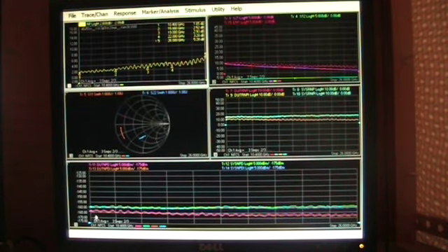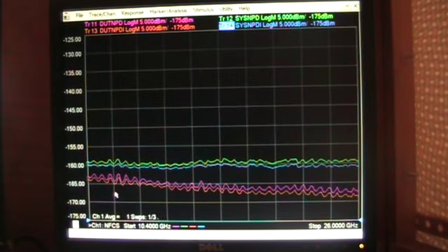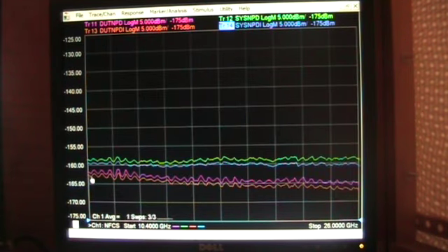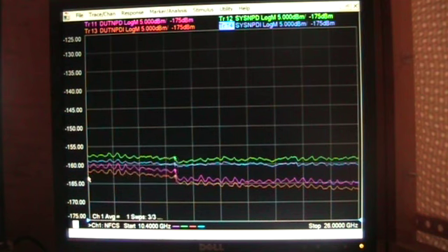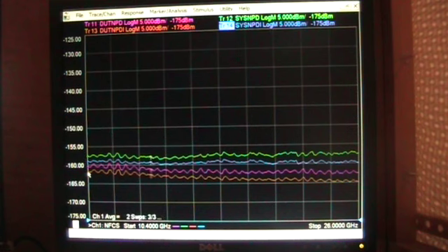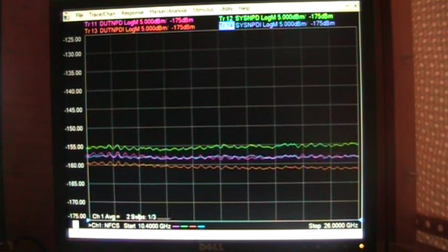We can also look here to see where the absolute noise is, and you can see that the orange line, the DUT NPDI, once again this is in dBm per hertz. At 10.4 gigahertz we're measuring something on the order of minus 162 dBm per hertz. That gives us a certain amount of confidence that this is a half decent number. So we're not flirting with the measurement floor that we saw earlier. It was on the order of minus 175.